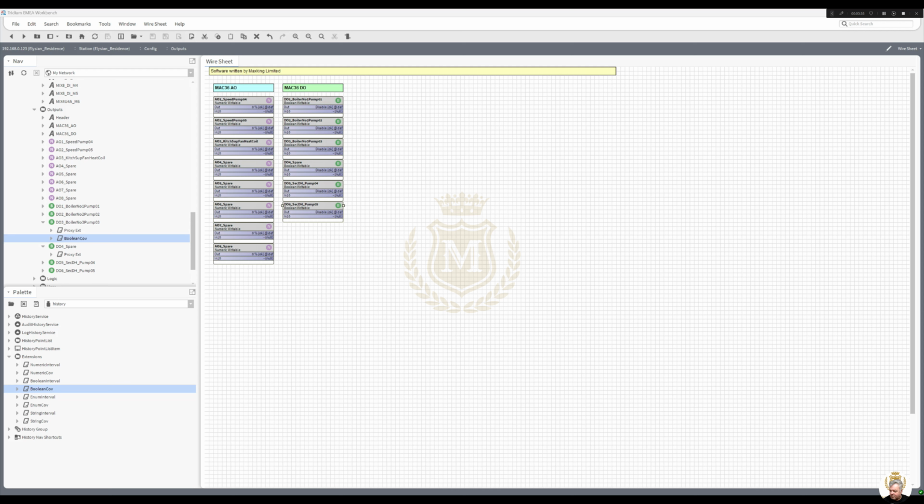Right, I need to go back to that drawing. So with DO5 and DO6, that's modules. That is universal input, so it's got to be that. Pump 4, pump 5, and then kitchen supply fan and kitchen extract fan is 7 and 8.